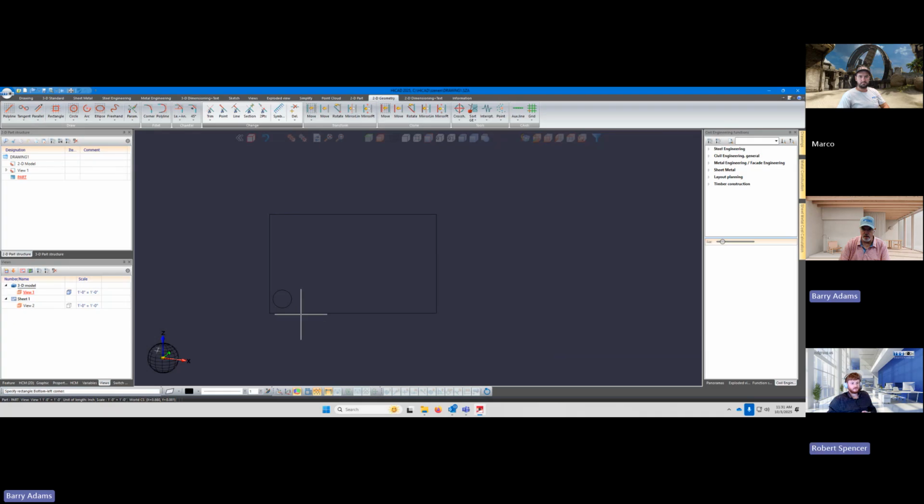I'm going to tell you, it's going to want you to click and release, drag a box, and then click and release. Oh, so I've got to drag a certain way. Sometimes it wants you to hold it down, and it usually tells you. In this case, specify rectangle, bottom left corner. Oh wait, no, now it zoomed right in.